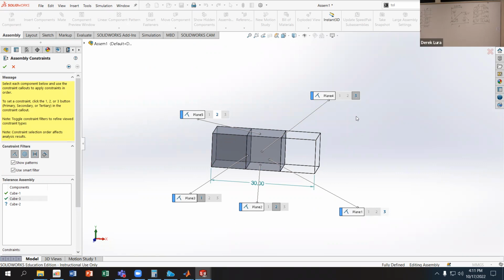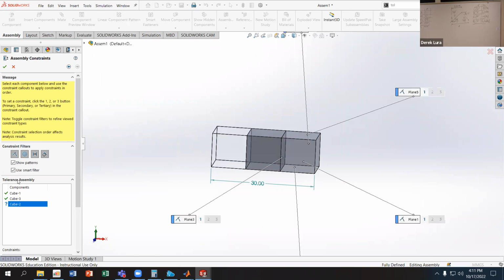So first part moves by a certain amount based off of all the different planes that are defined in the tolerance analyst tool. When those planes move, how do the planes on the next part move? That moves the origin of the next part, and then it applies that part's dimensions, and then it moves on to the next one. So it's sequential, kind of like we do in our tables over here, going from top to bottom. That's got a green check, we'll move to the next one.